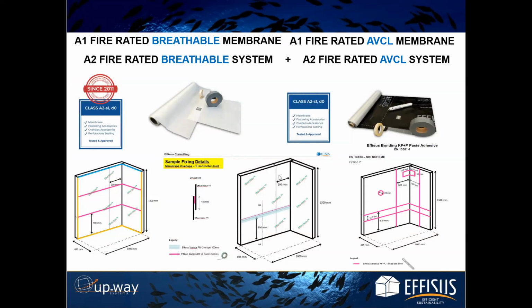As I said here, you can see we have an A1 fire-rated breathable membrane and an AVCL membrane, and has a system, as I said, simulating the end use on a facade scheme. We got A2, S1, D0. And here you can see how we have done our tests.